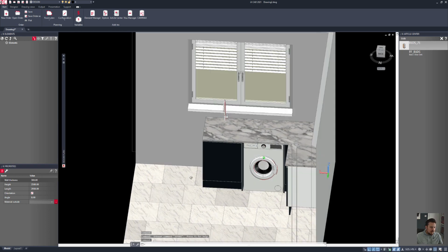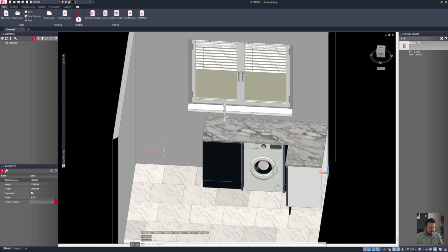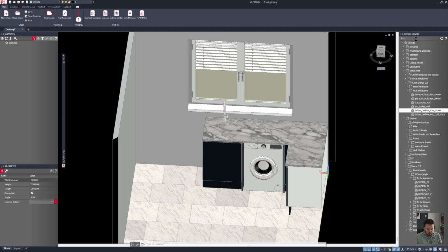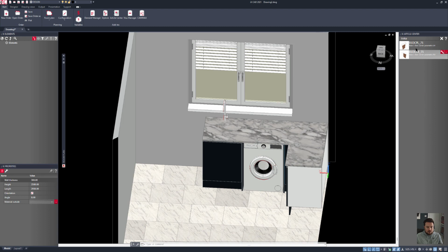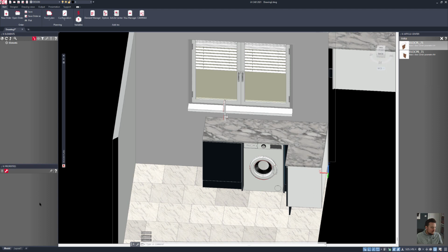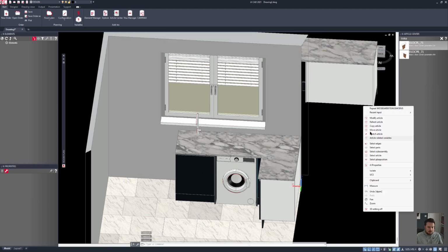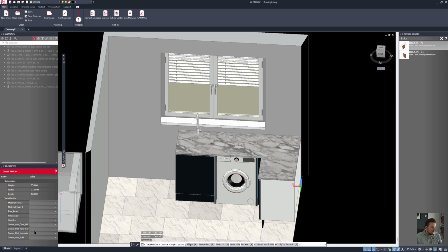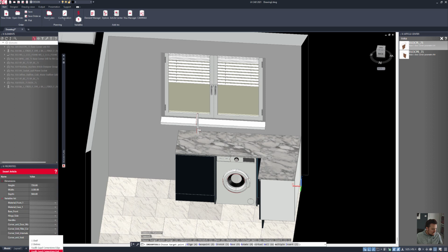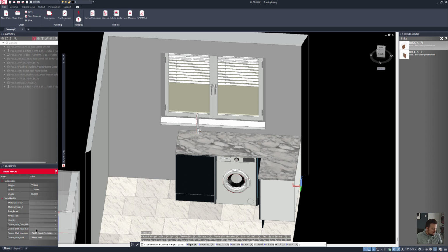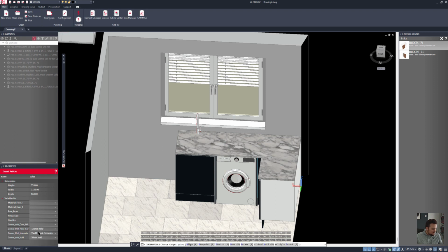So the next thing I want in here is another corner unit coming around here, and then I'll need some sort of infill on the other side. So I'll go back to my base 1 door corner parametric and pull through the opposing corner. And again, I can bring in my settings. So when I bring this in, let me just delete that one out, double click, and then down in here I want again a 50 millimeter void, and in this side I'll have the same Wolfsegel pull-out components in here. I'll say that my filler panel should be 150 millimeters, and I'll keep my door width the same as well.